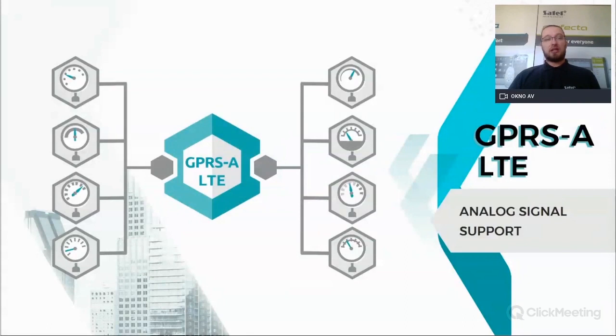You have a lot of information like temperature, amount of light, leakage. You have the possibility of a humidity sensor. Almost every type of analog sensor you can connect to this module, and then you can configure it to give proper information to the end user. For example, if a humidity detector says that 100% humidity is 10 volts and 0 is 5 volts, and you configure it, then the end user is able to see that humidity is 75%, not in volts, because volts don't mean anything to the end user. But 75% means that he needs to start the sprinklers, etc.